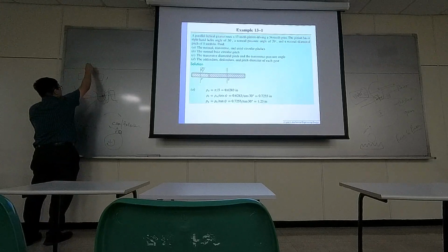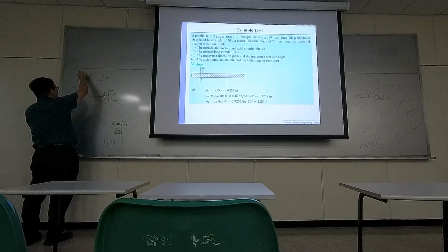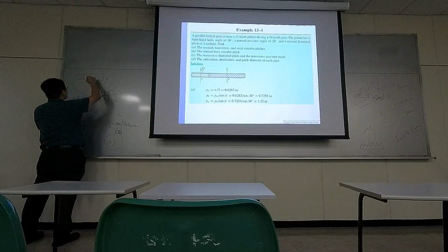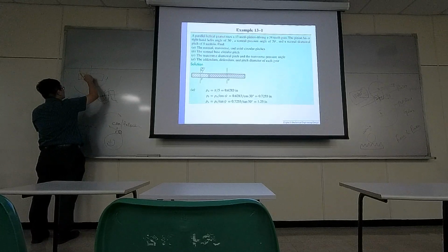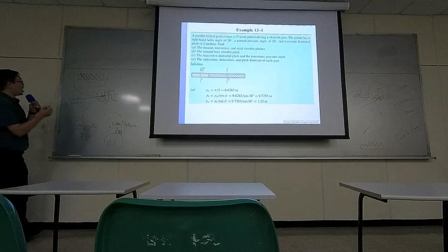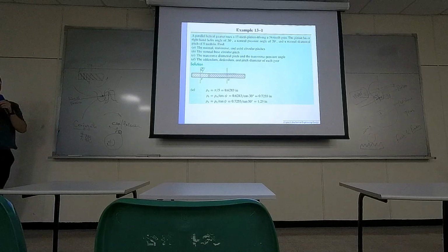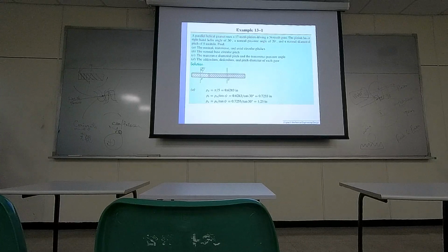Originally, this is your rotational axis. Originally, your teeth profiles are parallel to your rotational axis. But now they follow some kind of helical curve, so the teeth profile is now following a helical curve. Okay? When you do that, you will have this helical angle. By default, a straight gear has 0 helical angle. Now, it's telling you the helical angle is 30, like the drawing on the left.